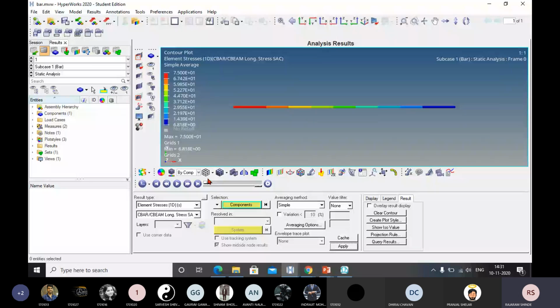Now, if we go to the next point, stress at D, and if we apply this stress, that stress will be 0, because your D point is on the neutral axis. Now next, at E point, you will get the negative stress. You can see here, you will get the negative stress, and it is also 75, because your cross section is uniform. Distance above the neutral axis and distance below the neutral axis, both distances are same. You will get the same negative stress, that is minus 75.